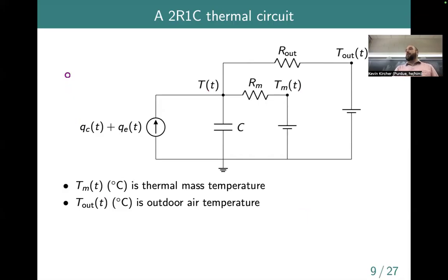Okay, so that is a 1R, 1C circuit. Now we can get progressively more complicated and add in different numbers of capacitors and resistors. The order of the equation is determined by the number of capacitors in the equation. I mentioned we're talking only about first order thermal circuits today, so they will only ever have one C, one thermal capacitance term. But you can get large numbers of R's and still get complicated looking models.